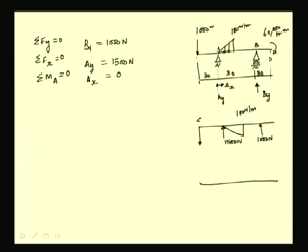At C we get the shear force as 1000 newtons from the algebraic relations by considering the free body diagram of a portion between, let us say, this C and A. Now, we see that between this point C and A there is no change in the load and we do not have any loads.